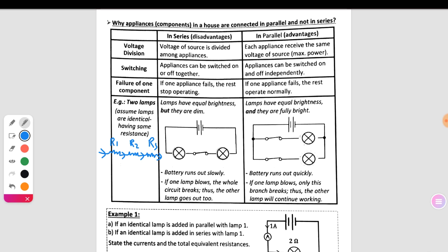When we put a meter in this position, and in this position, and in this position, and in this position, we observe that the reading does not change. This means that I is constant. I is constant in series connection. But when one of them is cut off or damaged, current does not flow through the circuit. This is the characteristic of series connection.